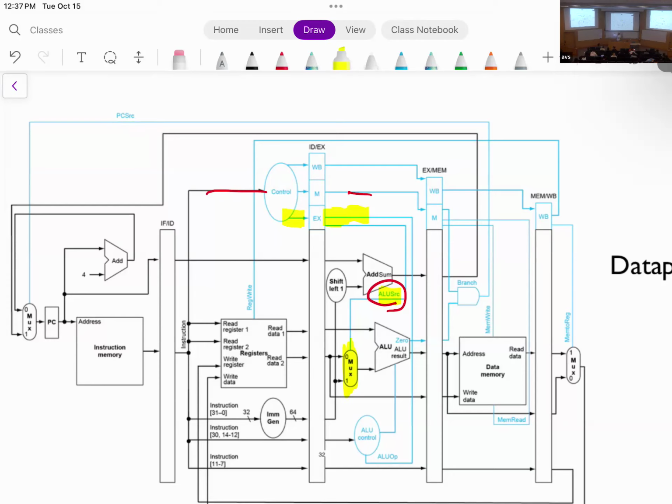The complexity of the pipeline design is that you will see different units, but each one is at a different clock cycle. Each one is using a separate instruction because now things are parallelized, right? Same story with, for example, ALU operation. But then you will see that the branch signal is used in the memory stage, and the memory to register signal is used at the write back stage.